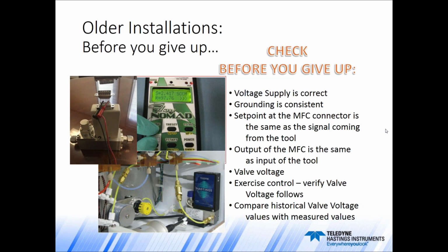Grounding is very important. I think Doug has mentioned how important grounding is. The negatives at the power supply, in a plus or minus 15 or in a 4 to 20 milliamp current installation, but grounding has to be consistent throughout the system and has to be consistent at the MFC level. That's something that you can very easily check with a breakout kit, like Doug said, available from both Teledyne and SemiFlow for loaner. It's something very easy. You can check with a voltmeter.